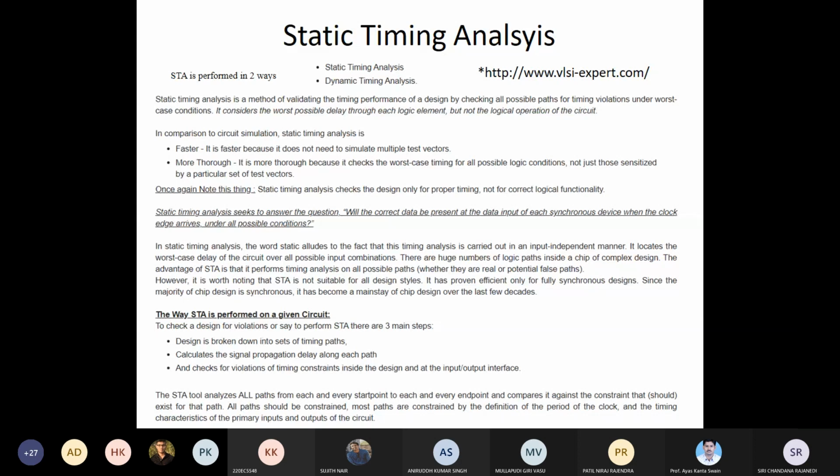So that is called dynamic timing analysis. But dynamic timing analysis always corresponds to checking the logical functionality of your design. Your time advances on the x-axis, but in the meantime, you are always checking whether your functionality is correct according to your requirement, according to your specification of the design. In contrast, static timing analysis works in a different way.